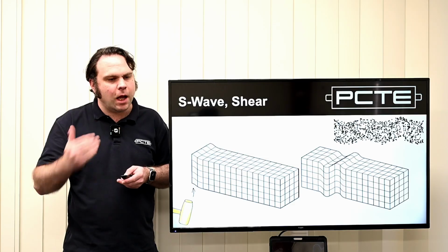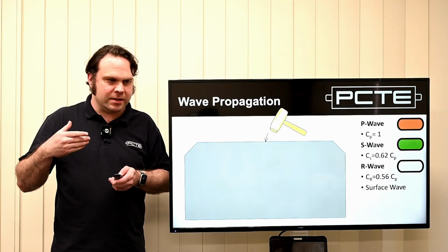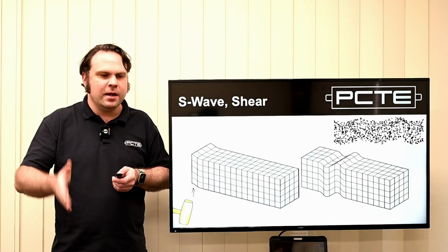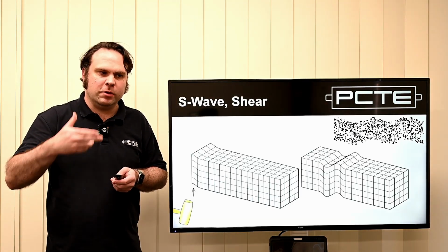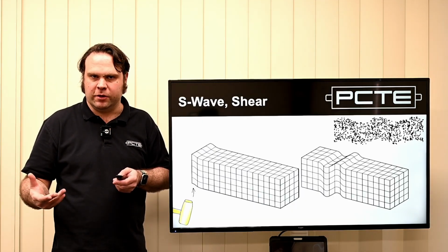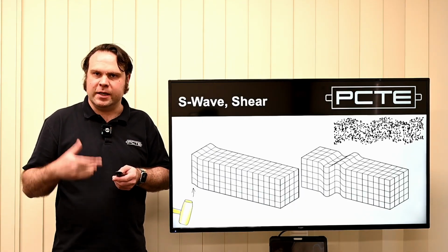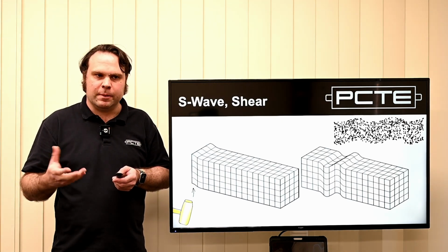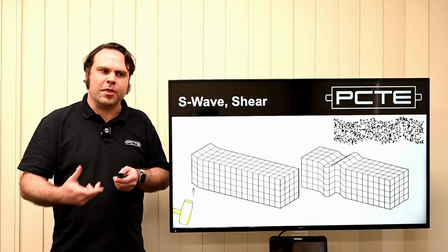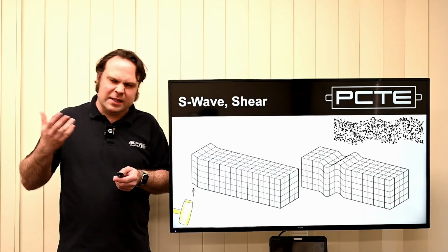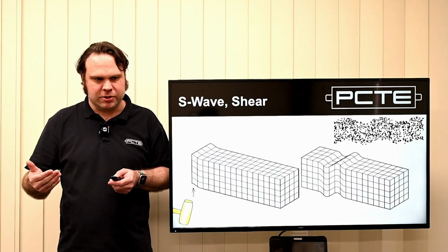Now, if we have a side-to-side motion of a source, we'll term that shear wave energy, which has different carriage properties and is quite commonly another form of energy we hear referred to as ultrasonic. Particularly the ultrasonic pulse echo devices that you will mostly see are actually shear wave arrays rather than sound arrays. It has a couple of property differences, the main one being in the speed of transmission.